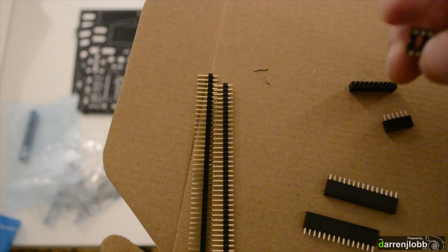You also need 3 of these. This is for the optocouplers, so you can plug them in and out if you were to kill one. Those little chips essentially isolate, because you've got 3 switches: a work switch, steer switch, and remote. If you were to accidentally feed those pins with something you aren't meant to, it isn't going to pop the Arduino, because this little optocoupler chip, which sockets inside here, protects it. If you were to pop one by using these sockets rather than soldering them directly, you can change them. And then you have some male ones, same thing, which you can use here and there where you need to be able to make connections.